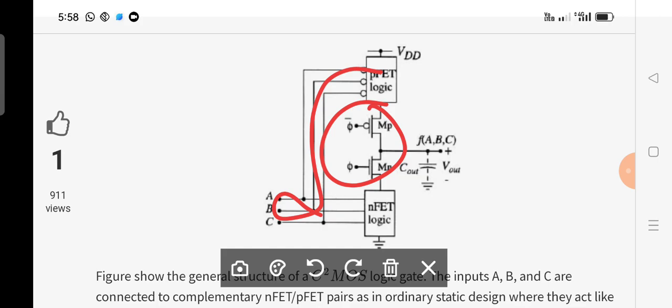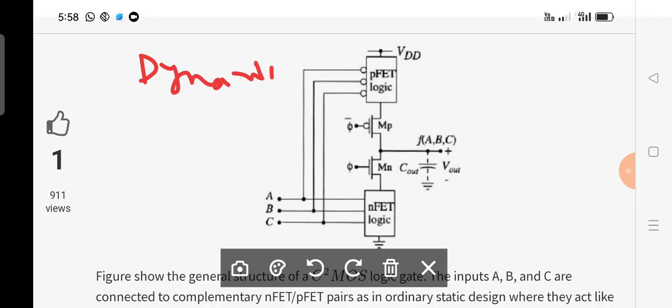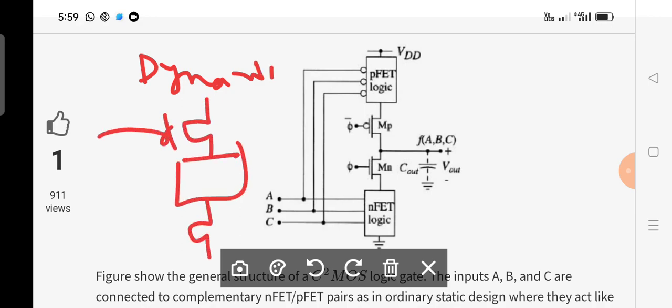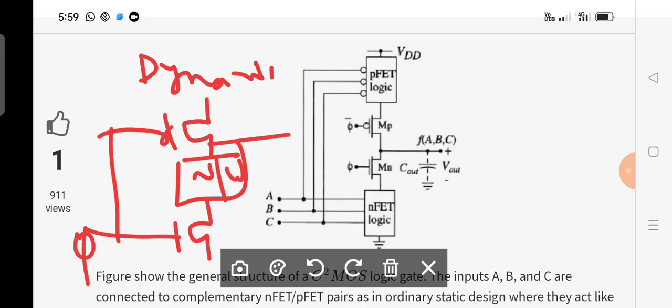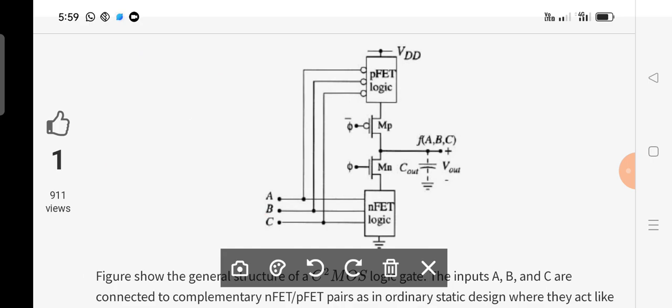This is one type of application of other forms of CMOS logic. You know very well what a dynamic CMOS is. You can observe that in dynamic CMOS you have a clock like this and a network in this fashion. Is it clear? You have only one clock, then you have a network. Based on the network you can take the output from here or else here. Is it understood? Now you can observe that here, to maintain the synchronization, they are going to use two clocks.